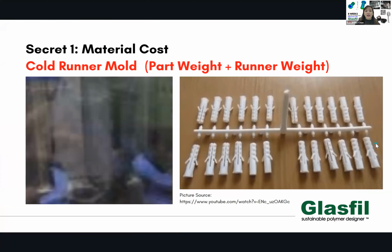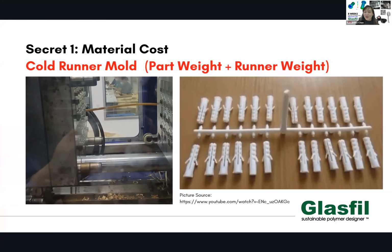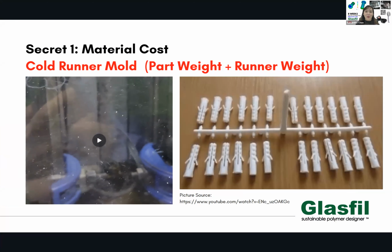Okay, so I mentioned the secrets. We actually have a lot of secrets in the plastic industry, because you ask a lot of people about plastics, and they seem not to be able to tell you how we calculate our cost. So before that, let me explain what a plastic runner is. Many people will say, I would like to develop things. There are a few terms that you commonly hear. You will hear about cold runner mold. Cold runner mold means this particular plastic part that comes out from the machine has this long run of material, which is not your part.